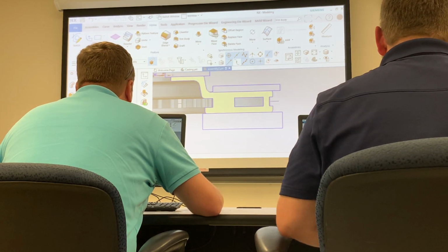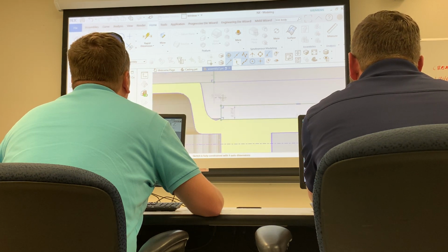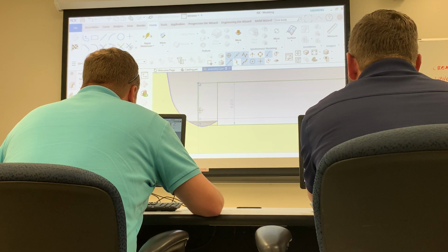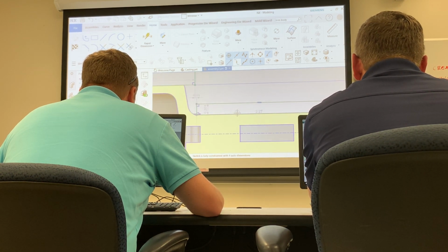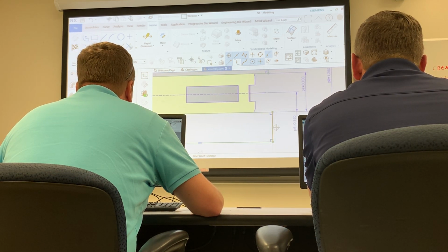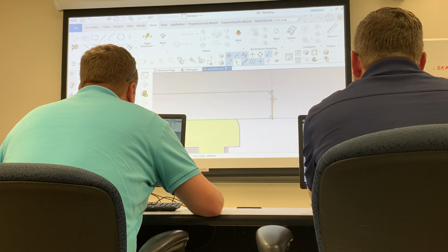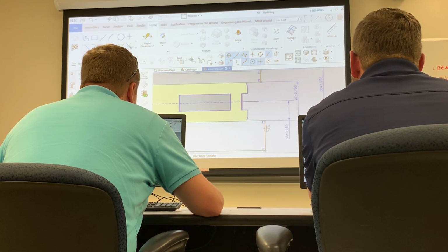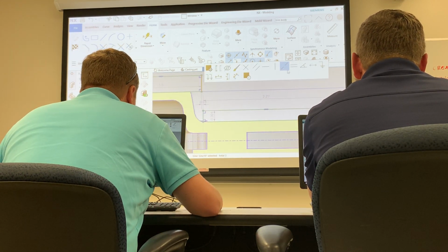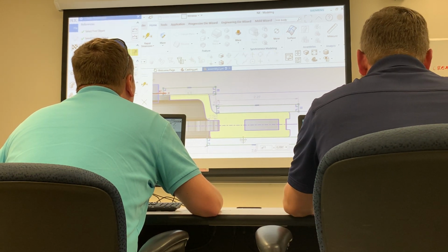So just out of an abundance of caution, and to show good form, I'm going to recommend that you always get rid of all of your auto dimensions, whether you think they matter or not. All right? So I'm going to start, just to get rid of them all. I want to try to use as much geometry as I can. That would be nice. Let's see, that line and that line. And I'll just make those equal length, all three of these. Equal length, that'll take care of that. And they're going to be 0.25, I guess.